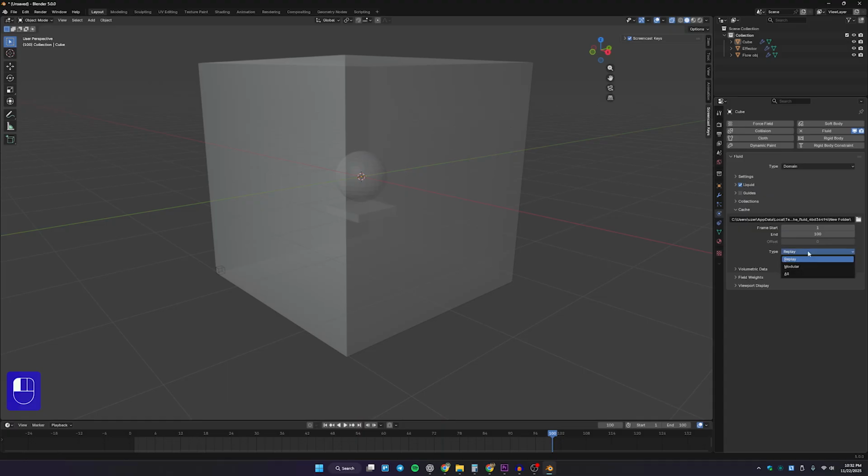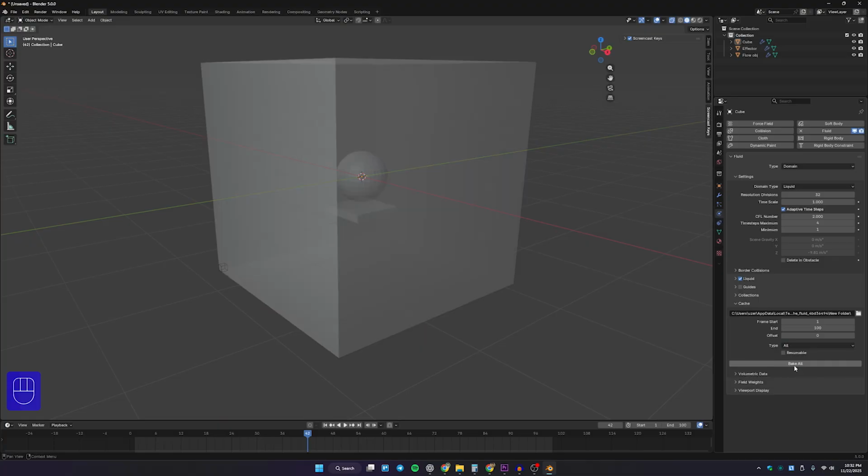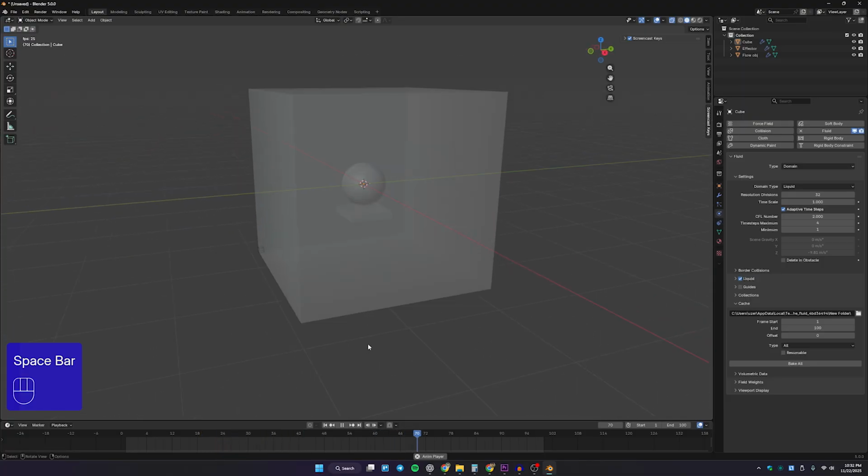The replay is the one we are having right now, which is always Blender's default cache in our system. So when you tweak some of the settings, Blender automatically caches it out again. But if I go here into the All option, my cache has just changed, and right now we have a Bake All button. This is a little bit different, because even if I go back to my first keyframe and play the simulation, it doesn't work like before.